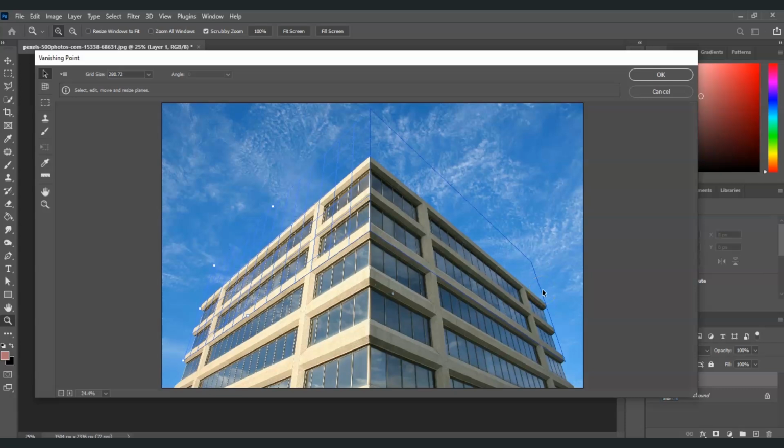The next step here is I'm going to click on the Marquee tool. So yes, this one is the Marquee tool, or press M for the shortcut key. Because our goal here is to create a selection from this upper part of the building with the grid line. So I'm going to click and drag this one, something like this, right? Make sure that you are selecting all the parts of the top of the building. There you go. Right, and then press Control plus C to copy it.